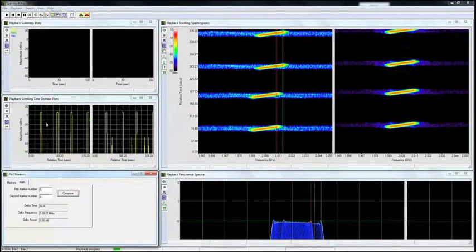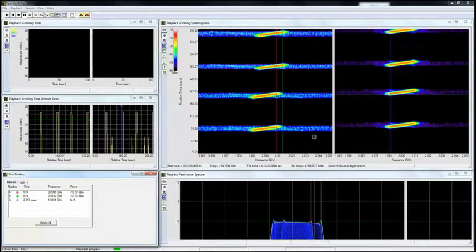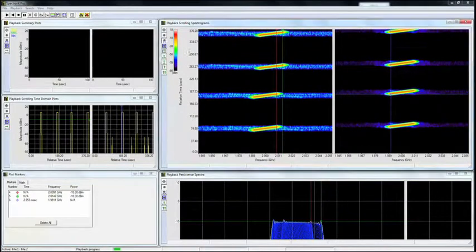Similarly, as we saw earlier in chapters, in the time domain plot, we can go ahead and place markers, in this case, not only within individual channels, but we can place markers in multiple channels. And if I wanted to make difference measurements between any of the two markers, whether they're in the same channel or in different channels, and again, as we saw previously, move those markers anywhere that we want so that we can make difference measurements very easily and compare one set of markers to another.